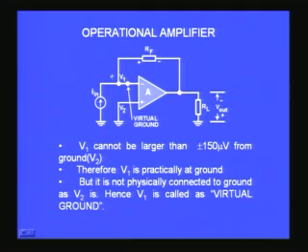Why is it negative? Because current is going from this end to the other end. Whenever current is entering a point, that point should be negative. Whenever current leaves a point, that point should be a positive point. So, in this case you find the current is coming towards this end, therefore, this end is lower in potential compared to this potential, and this is 0, therefore, this has to be minus.